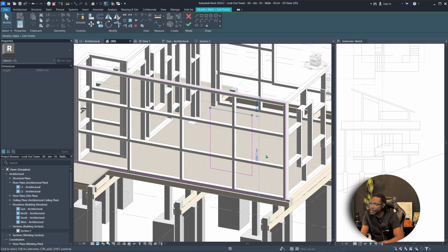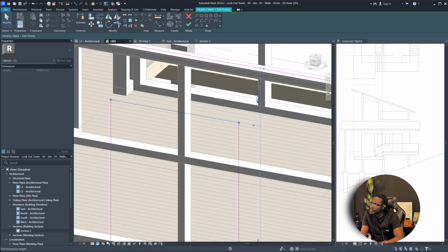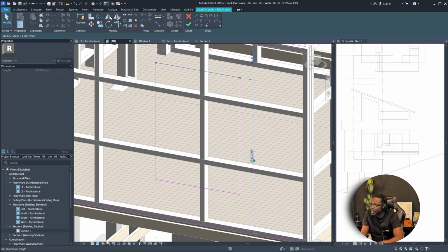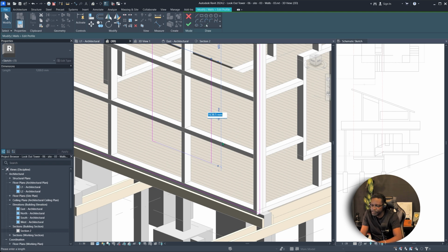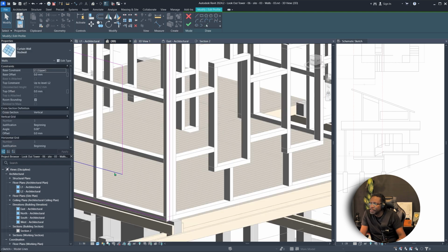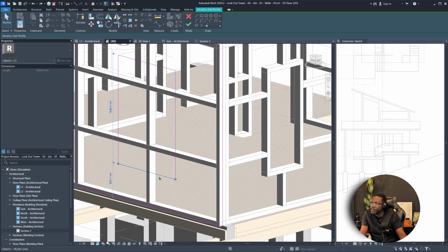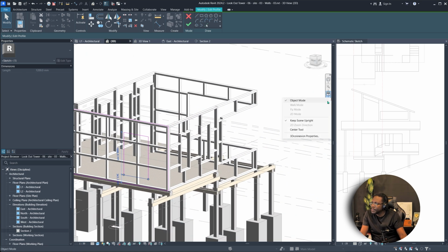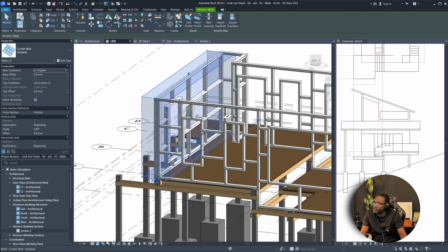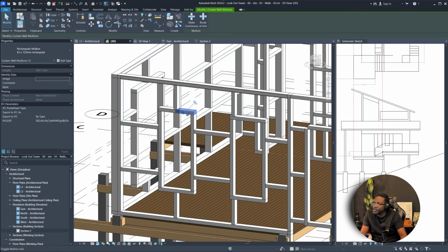All right. And we can make the height. Let's adjust the height from the floor to be 600. And let's adjust the height of the window to be 1800. Actually, we want to adjust the bottom to be 18, so we keep the top at 2 feet. All right, let's go back and edit these windows here.